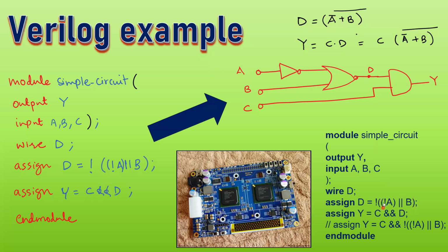So I have two parentheses here, these two parentheses, and again an opening and closing one. So don't get mistaken here. If you miss one parenthesis, when you compile the code, you will run into an error, but that can also be solved because the tool will tell you, okay, you have some error in closing and opening the brackets, but you have to be sure. And then for this final complement, I am assigning here again the not operation.